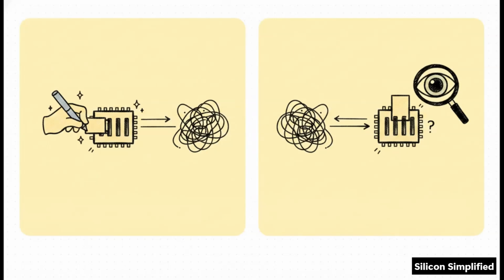Think about the pure symmetry of the UVM Register Sequence API. When you're writing sequences for hardware registers to poke and peek at your design, you really don't want to get bogged down in routing logic. A write sequence naturally uses write_reg, and a read sequence uses read_reg. Using these dedicated, symmetrical methods keeps your stimulus incredibly clean, super readable, and focused purely on the data being moved